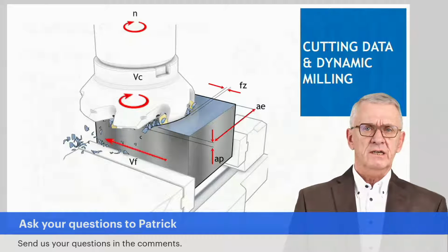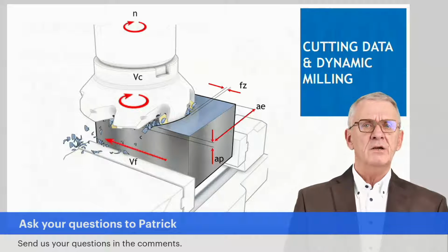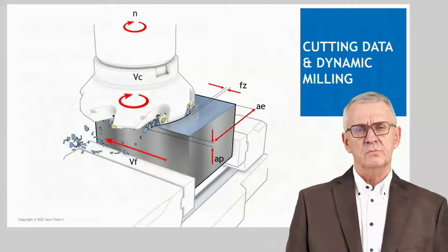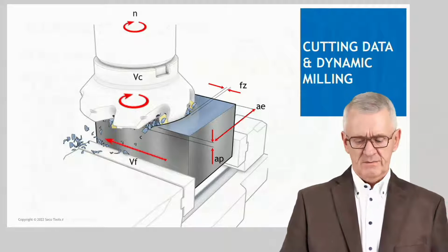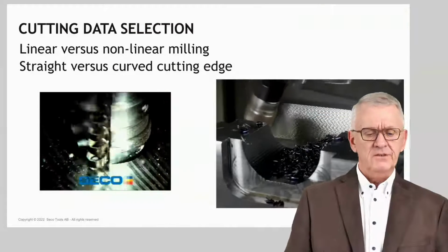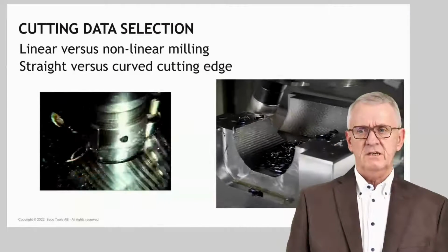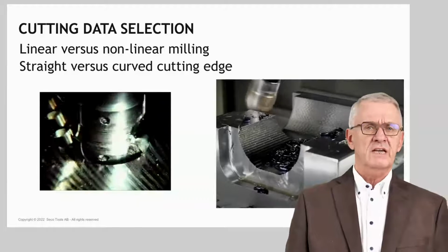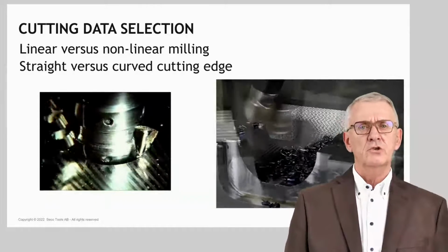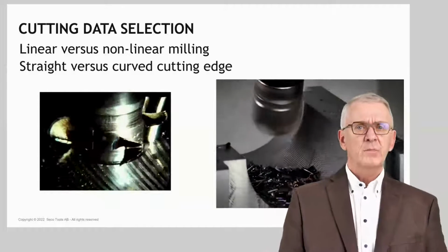Cutting conditions, cutting data is a chapter on its own. And by the way, I started to talk about dynamic milling. I want to spend a couple of minutes here again on dynamic milling. Cutting conditions. First of all, if we talk about cutting conditions, be careful how you define them, because today we talk not only about linear milling, but we have also non-linear milling operations.